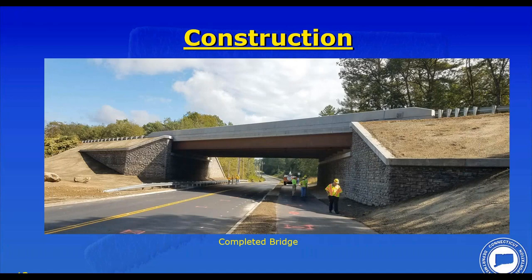As far as the superstructure, we went from concrete to steel, not because we hate concrete. Don't get me wrong on here. It had to do with the fact that we increased the span about 20 feet. We wanted to keep the clearance as high as possible. And the steel girders allowed us to get more vertical clearance than an equivalent bulb T girder. So it was a case of geometrics and clearance that was the reason to go to steel.